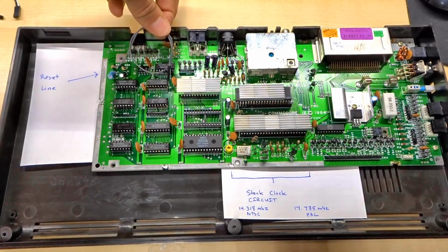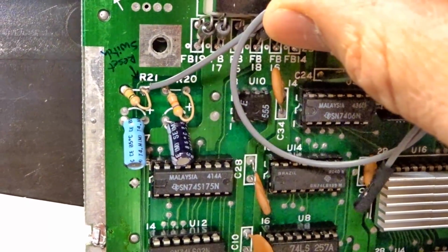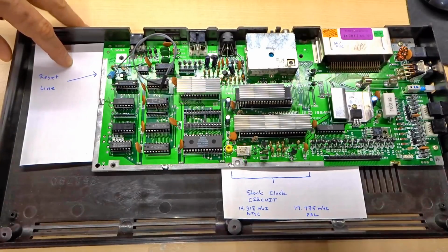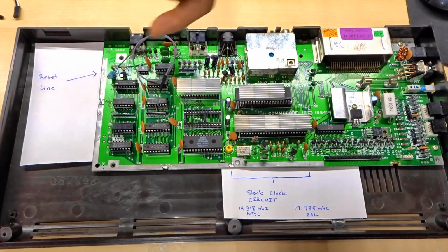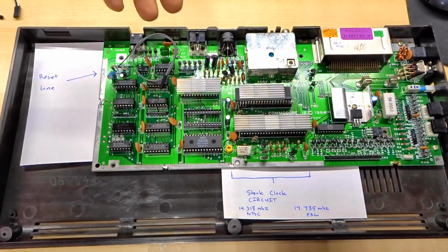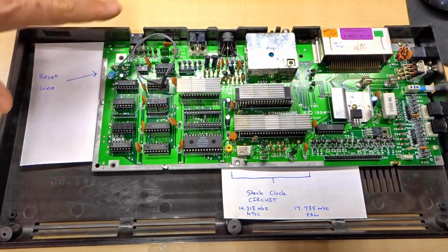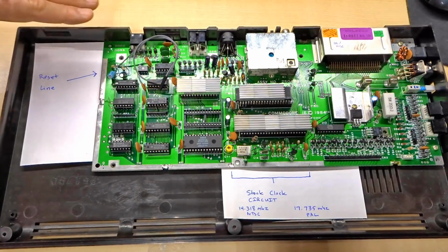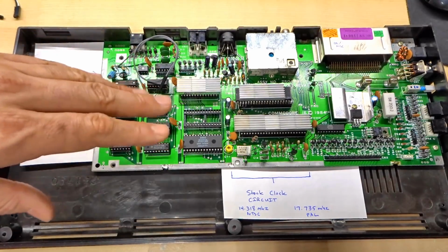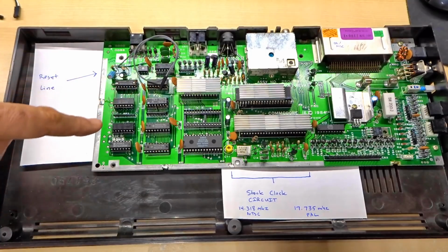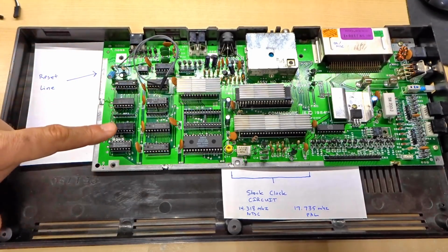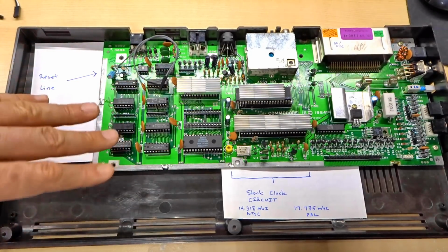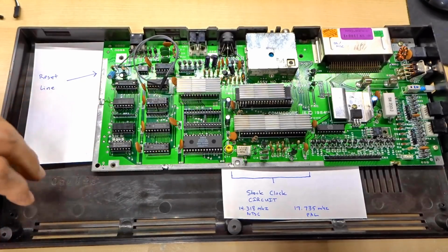On the right you see a gray wire I have soldered onto this resistor. This allows me to pick up the reset signal that comes from me pushing the reset button on the side of the machine, and also allows the microcontroller to drive this line low to reset the entire computer. Unlike the Commodore 64, the C16 does not have a restore key, so I decided to use the reset button itself to allow me to select which kernel and mode the computer is going to run in.